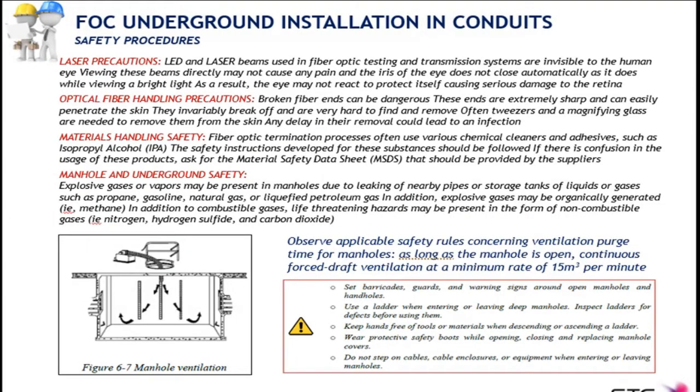On this slide, we're going to see some safety procedures while installing cables underground. The first point that we have to highlight here is to warn you out on the fibers that may transport light outside the visible spectrum. So you would be unable to see the light coming out. And if you look directly at the fiber end or to a connector, that may severely harm your eyes. So never ever look at the end of a fiber or a connector.